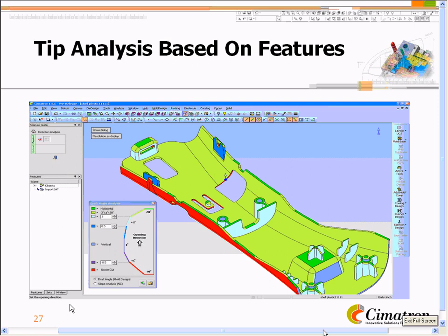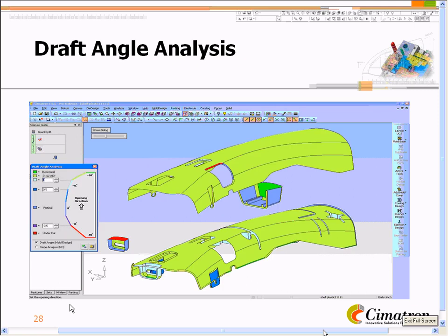The system will allow you to interrogate the data itself, find the feature that you feel most likely will create the best tip condition, and here we reprocess or recalculate so the system shows us what the tip is. So maybe I'm off like 5 degrees in order to rock that thing around to its correct position. Compound tipping is very common, where you have to go 2 axes to get the right tip. That is saved right now in the system. It knows that axis of motion and will allow me to design based upon that being tip position.